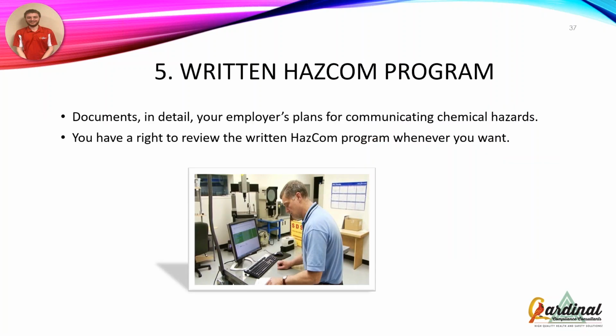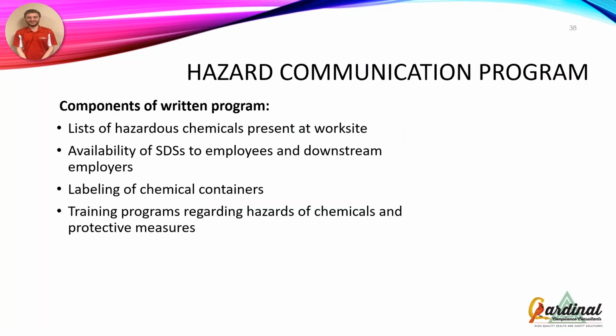Okay? Now, the written HAZCOM program documents in detail what your plans are for communicating those chemical hazards, because that's what the HAZCOM program is all about, communicating those hazards those employees are exposed to. Okay? And you have a right to review the HAZCOM program whenever you want. That goes for all employees as well. As Rich mentioned earlier, your safety data sheets have to be readily available for any employee. Well, that goes for your HAZCOM program as well. They have to be able to review that if they so wish.